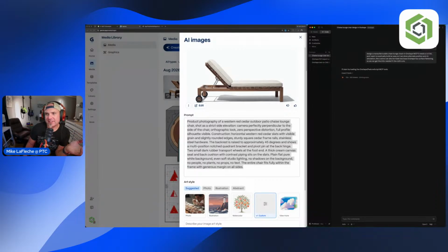Of course, you're not going to run a simulation on wood that's going to be nonlinear. It's got grain direction and is not isotropic, things like that. So there are certain assumptions you can make, though. Like, you can do beam analysis and get basic checks done on this design. If you're going to have a 200-pound person lay on it, what would happen, right? What would happen if it was operated in ways that we don't expect? So we can ask it these questions while it's doing this.